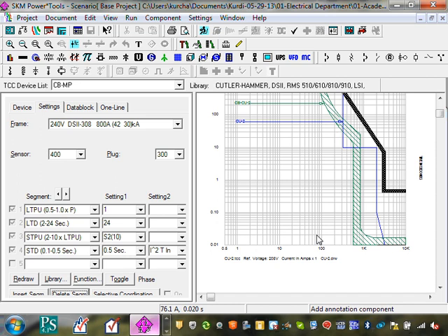If your equipment is not rated for arc, or what they call draw-out ANSI rated switchgear, and you do this in your circuit breaker, you have just burned your equipment. So that's what the instantaneous circuit breaker is. That piece here is my instantaneous.